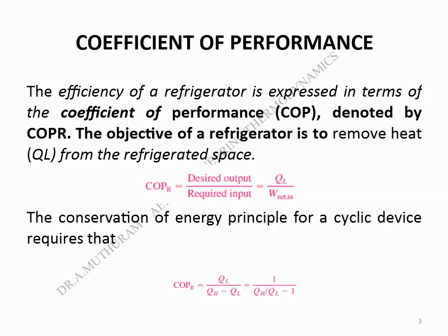Coefficient of performance. The efficiency of a refrigerator is expressed in terms of the coefficient of performance, COP, denoted by COP_R. The objective of a refrigerator is to remove heat Q_L from the refrigerated space. The COP of a refrigerator is the ratio of desired output to the required input. The conservation of energy principle for a cyclic device requires that COP equals